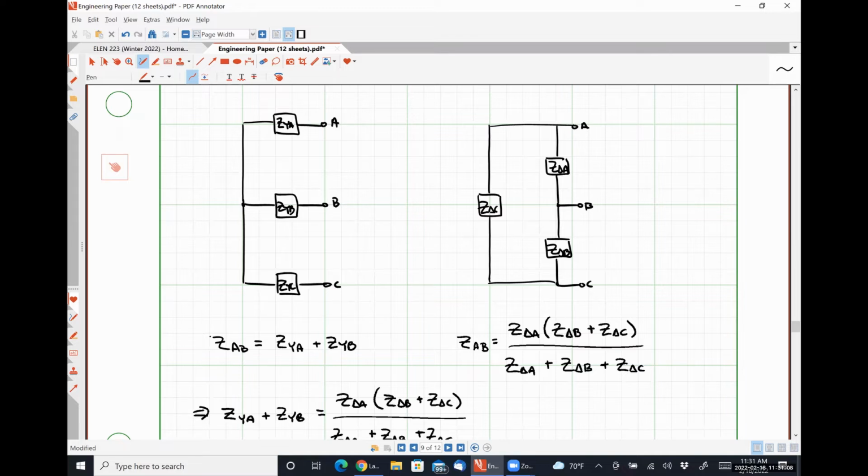So if you wanted to apply this, in my opinion, the best way to do it is to label your terminals A, B, and C, and then put in the new thing between terminals A, B, and C, very similar to how I encourage you to do a source transformation. This is a transformation: literally disconnect your original network, do the transformation, and then replace the original network, making the exact same terminal connections as you had previously.